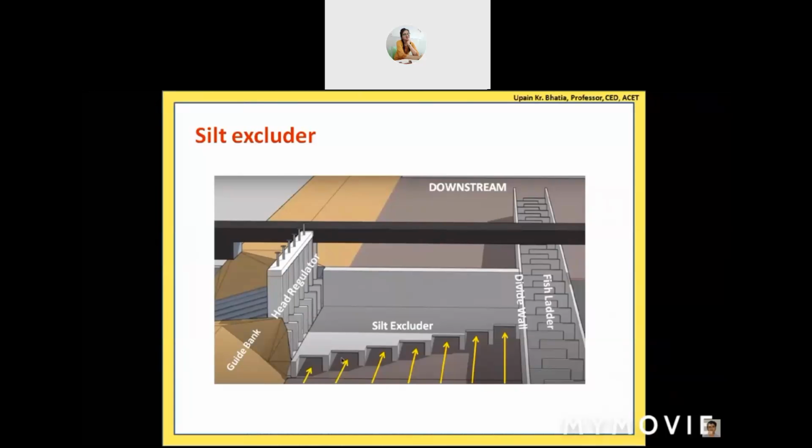Okay, but the upper layers, which are shown in blue lines, the blue line does not mean that it is 100% free of silt. It is comparatively silt free, as compared to the bottom layers. So the concentration of the silt in this particular portion of the water is lesser as compared to the bottom layer, but the suspended silt can still enter this canal through these head regulators. The water is not crystal clear. It can be turbid also. That means sediment can enter into the canal also.